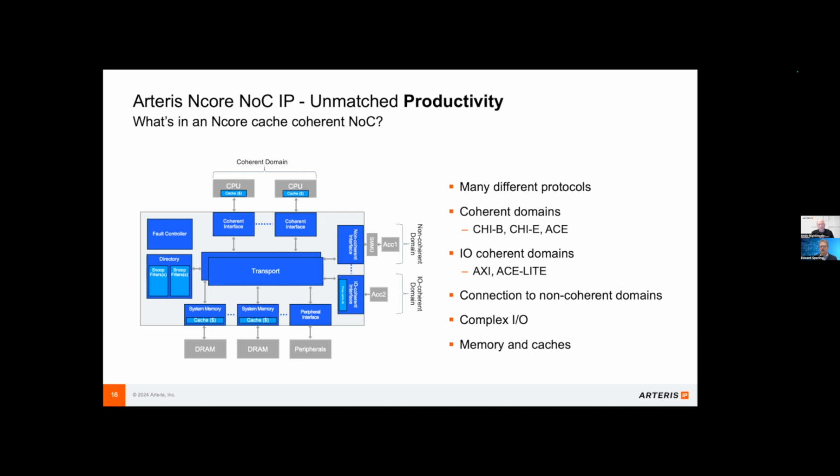And of course, the important point here is the memory and the caches themselves. So what we use is a number of internal caches. Those arrange and manage the I/O device data coming in. We coordinate that with the CPU data coming in from its own caches. And we actually make that really efficient. Our take is basically making that efficient, having a directory of where all this data is stored. So you can snoop into the different caches of the various parts of the system and actually very efficiently identify where that data is coming from, or whether that data is invalid or needs flushing or refreshing from the DRAM.